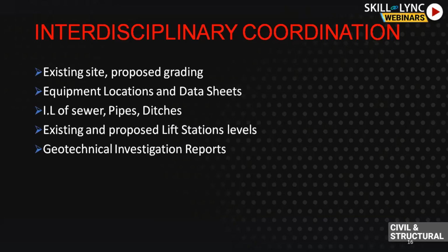So data sheets are required from process departments. These data sheets will tell you what is the size of the tank, what is the frequency of this tank, what is the loading of this tank. Many sewer pipelines will be coming. You need to check the invert level of these sewer pipes because you will be making opening details for this.